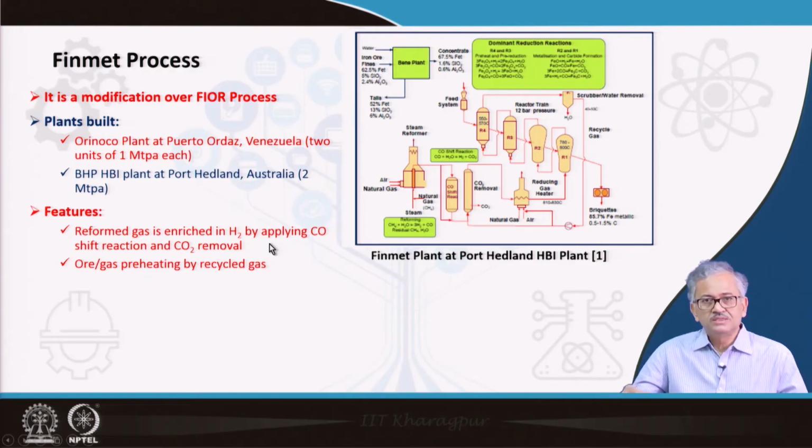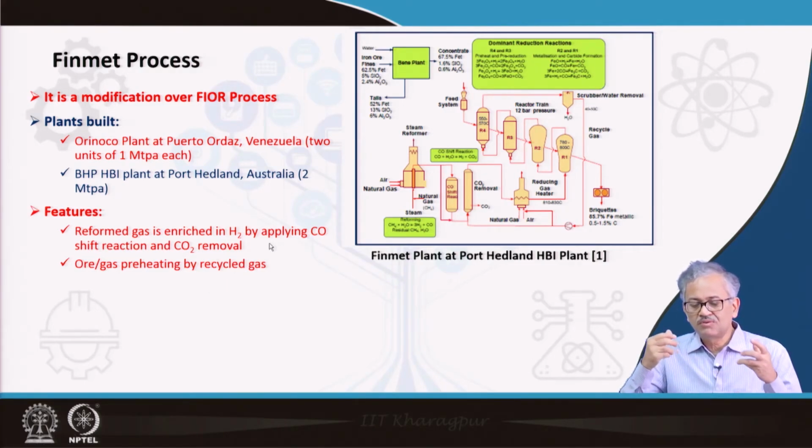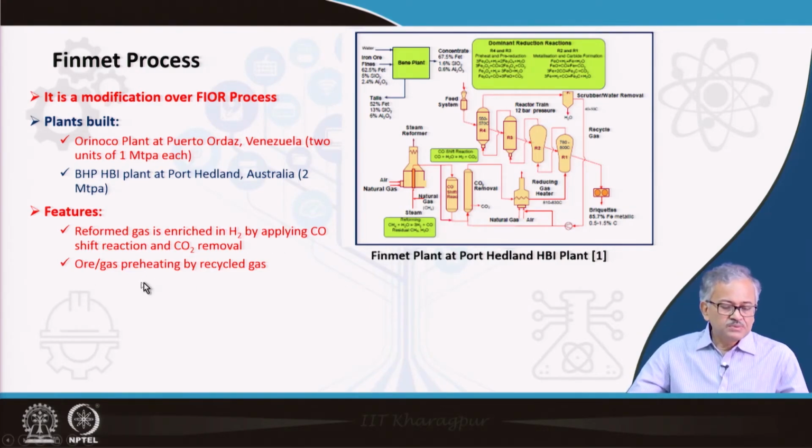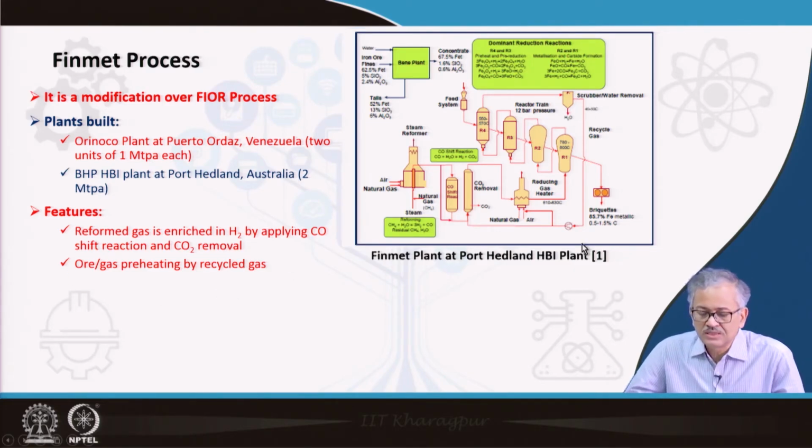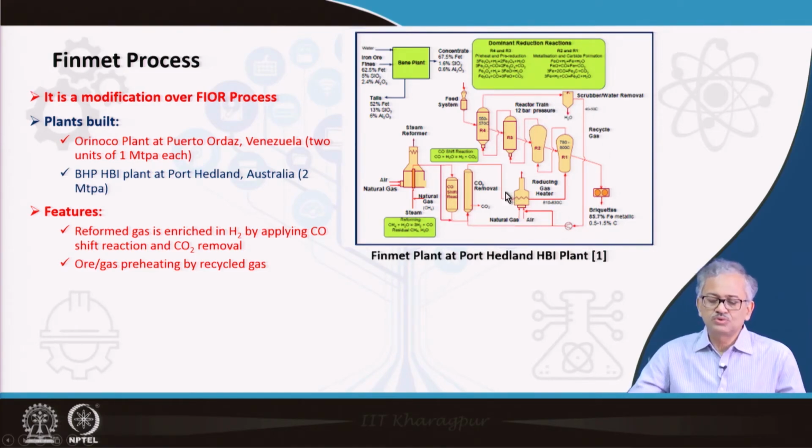And so the feature is the reformed gas is enriched in hydrogen, applying the CO shift reaction and CO2 removal, and ore and gas preheating by the recycled gas. One thing is that if you can enrich the gas with hydrogen, then as I said, you can carry out the reaction comparatively at lower temperature, so the sticking problem of the particles will be less.